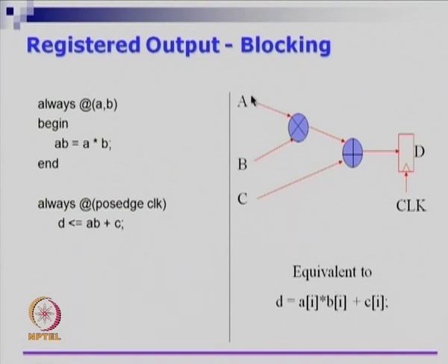So you are taking inputs which are all given at one instant of time, that is what this I means. So this I is not a subscript within A, this A of I is time. So at time I, whatever A, B and C, if they are all kept stable, then it takes those inputs A and B, multiplies, adds it with C, and that will go as input of this flip flop here. In the next cycle, this value will get into the register. When the next clock pulse comes in, it will go into the register.